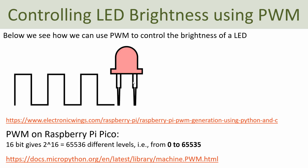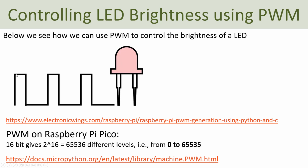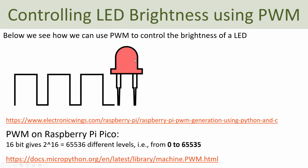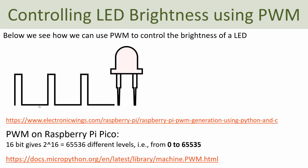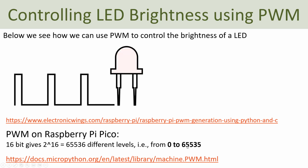So here we see the principle of pulse width modulation and how we can control the brightness of a LED. Basically we control the pulses, and these pulses are either on or off, and the longer the pulses are on, the higher the brightness is, compared to when the pulses are mostly off. The Raspberry Pi Pico has a 16-bit interface. This means we have 65,536 different levels, or basically we can control the levels from 0 to 65,535.